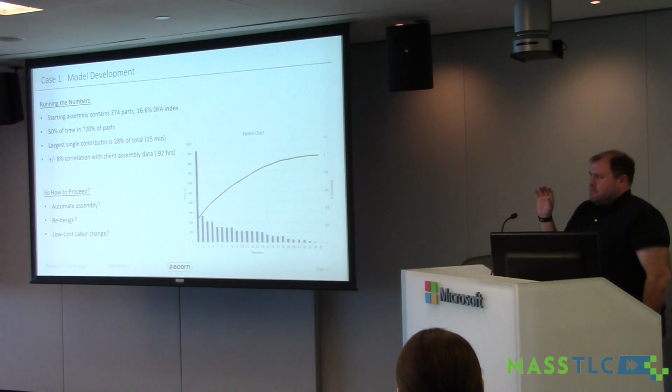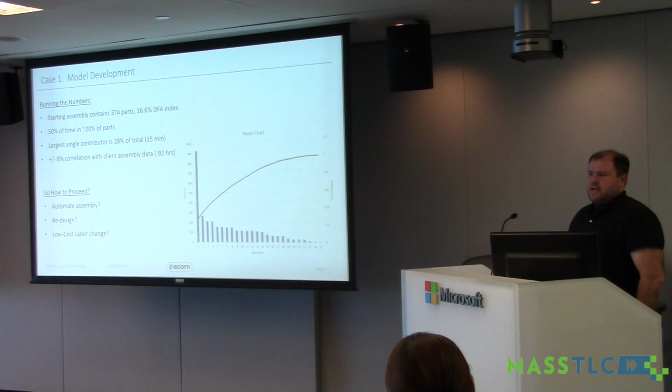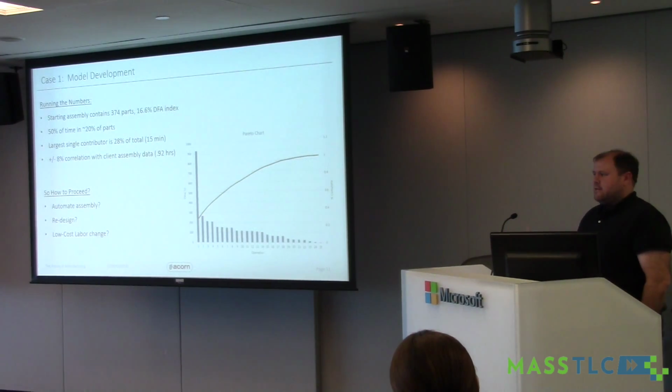So number of, did I get this right? Minimum theoretical parts over actual parts. So things like screws, things like brackets, things like spacers or other things that don't really do the function of the assembly but are there just to kind of put it together. Those are the overhead. And you'd like this to be as high as you can. Ranges in the 30% is really good, and 5% is kind of bad.